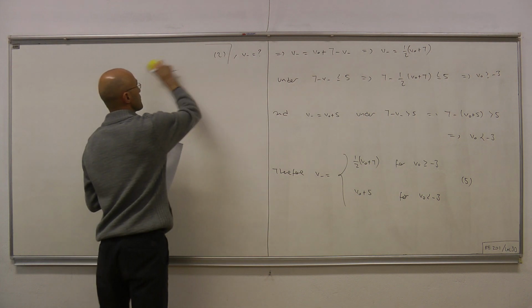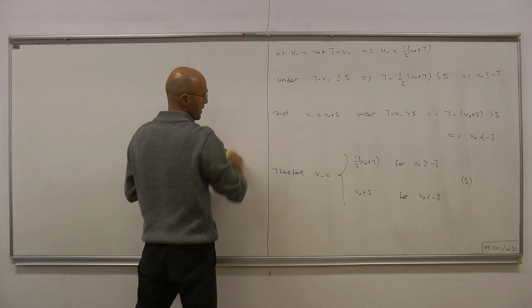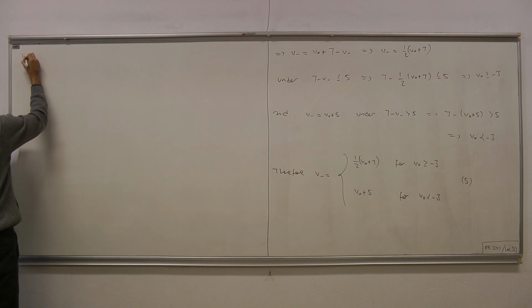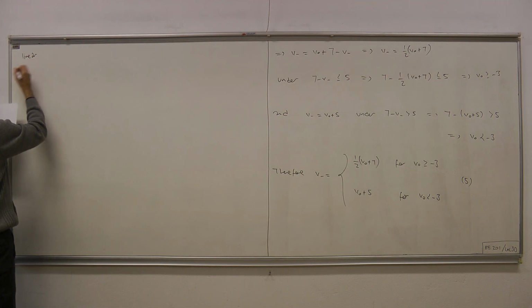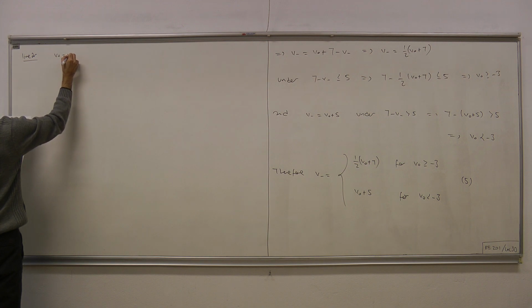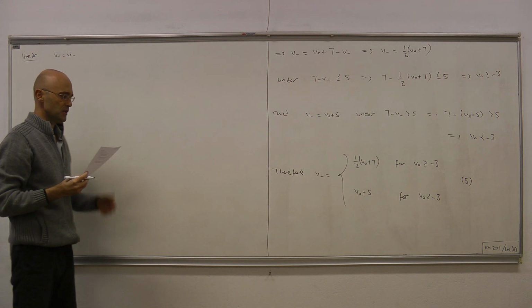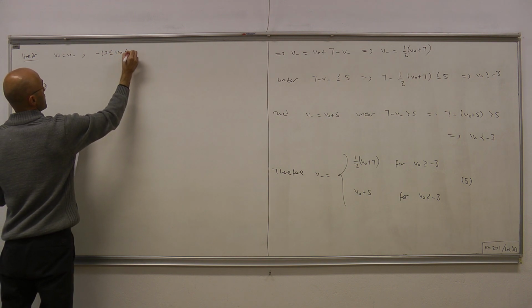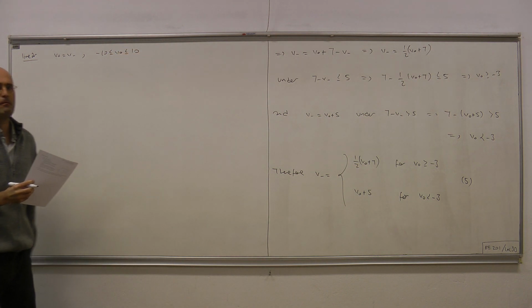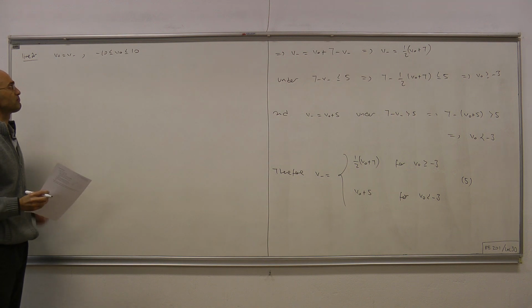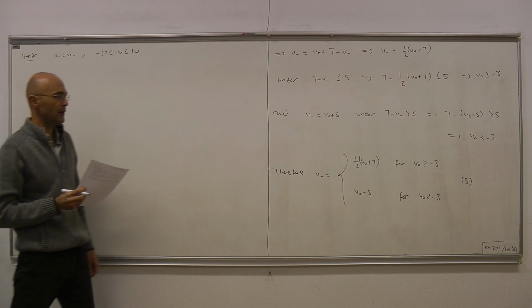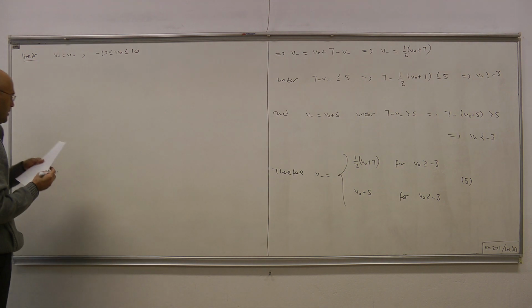That's V plus, okay, 1/2 V in, and here we have V minus in the region where we have V plus equals V minus, and V out is between minus 10 and plus 10 volts. Okay, now equating V plus and V minus gives us the relation between input and output.